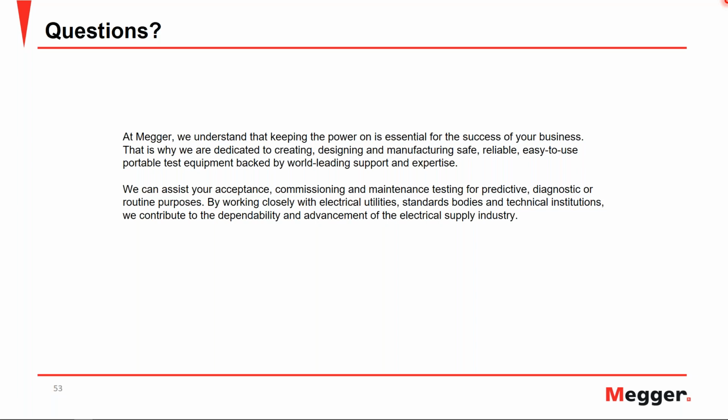And I'm not talking specifically only about transformers. In general, there are a lot of other methods available to check the condition of insulation. PD is another method that you can use. But when it comes to power factor testing, the reason why it is so popular is its ability to trend and analyze the measurement.